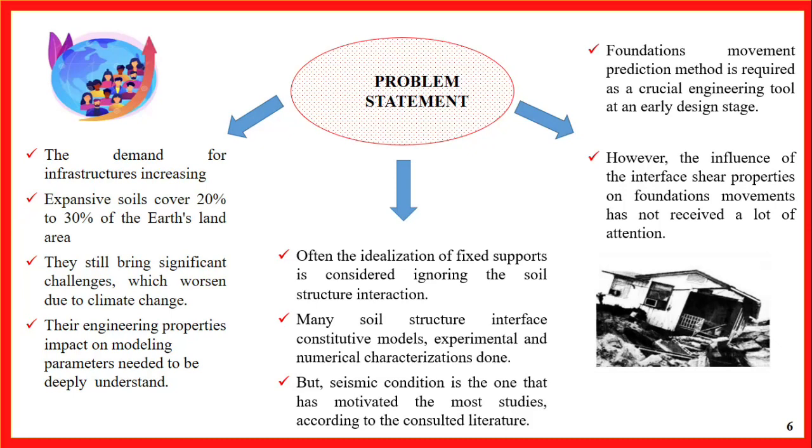Okay. So now the statement you are adding after the first one, where you are saying idealization of fixed support: However, for buildings resting on unmodified or partially modified expansive soils, failure due to shrink-swell soil behavior is imminent, as shown in the figure, as shown in the photo alongside. Okay. Then you move to prediction method for ground foundation movement.